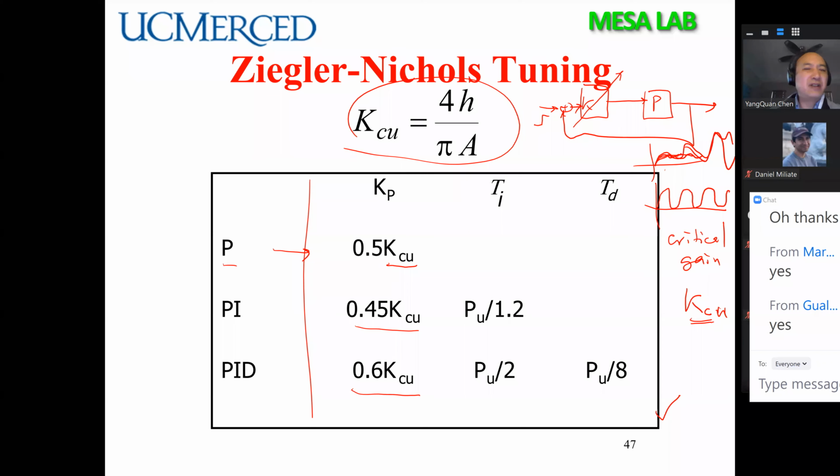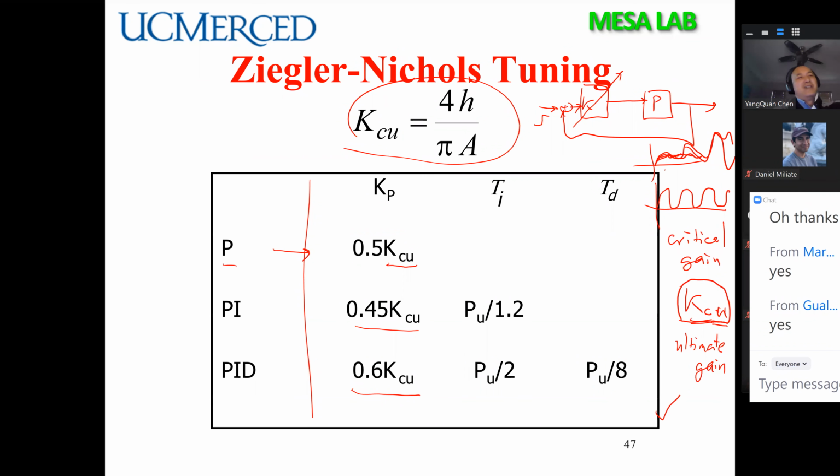Some people also call this the ultimate gain, because if you have a gain bigger than this KCU, the system will blow up. If the gain is smaller, then it will oscillate and die out.